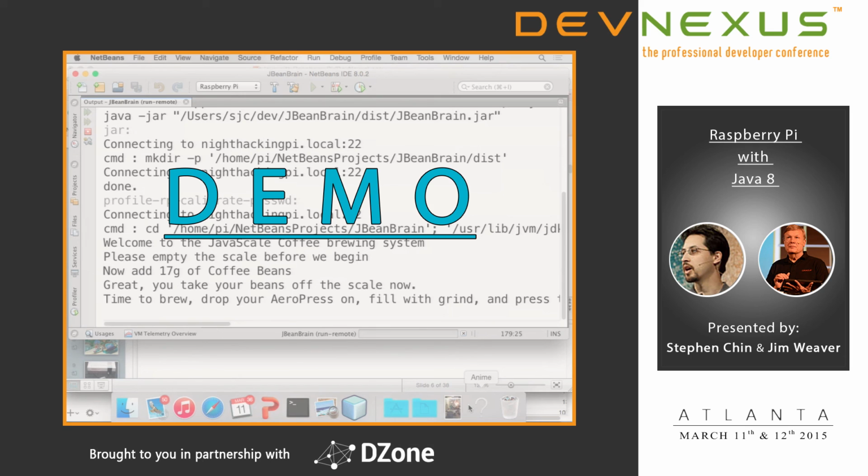OK, so it's done printing and it's cooling, but you can probably wrench it up a little bit before it cools just by grabbing the tabs and yanking it up. Start at one corner, and it should just start popping after a while. It's pretty hard to break it. You can put some strength into it. Usually it takes about 3 minutes to cool to the level where it will just naturally pop off. So, there we go.